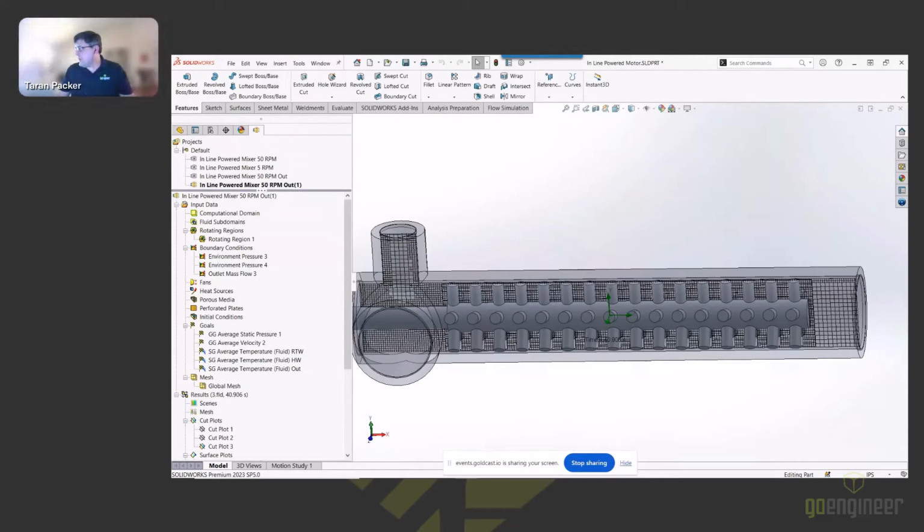Okay, last question I have up here is, he asks, so if you have a low mesh resolution, have you tried thickening the mesh and comparing simulation results? Honestly, in these particular examples, I did not do that. That's called mesh convergence analysis. In mesh convergence analysis, what you're doing is you're doing several simulations. You need at least 3 to compare properly. Sometimes I even go up to 5 or 7 simulations. And the only thing I'm changing between the different simulations is the mesh density. So I will increase the mesh density in each new simulation.